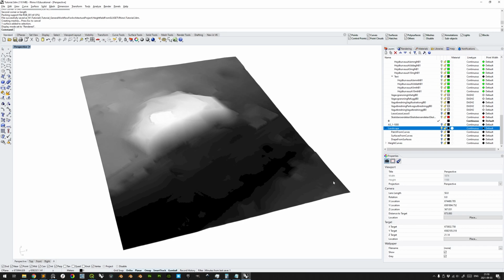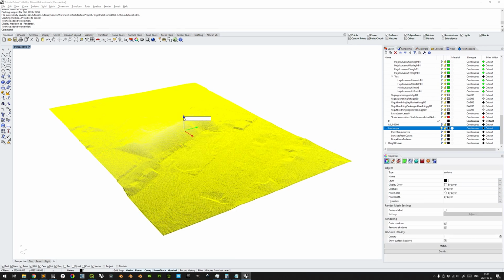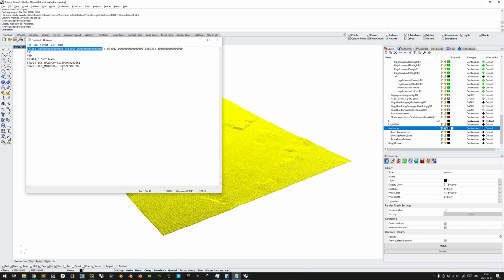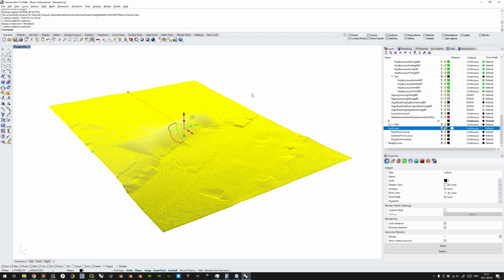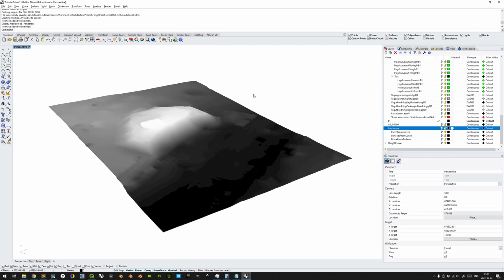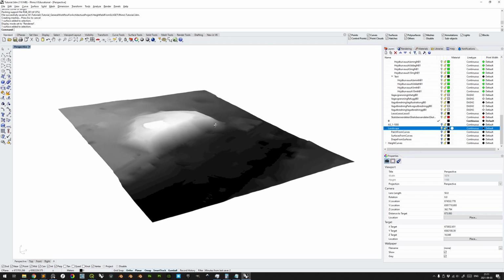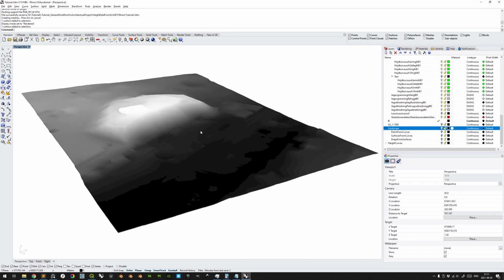But this texture is solely used for us to, for future operations, determine whether correct texture mapping has been applied or not. More on that later. Click the landscape, move it up precisely or rounded to a reasonable amount. The minimum value here for the Z height, so 6.02, and then we should have complete concordance with the actual landscape.